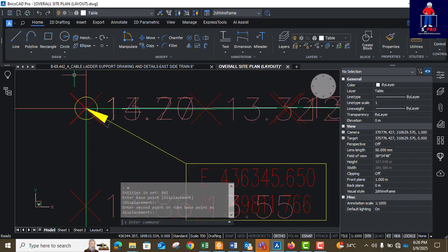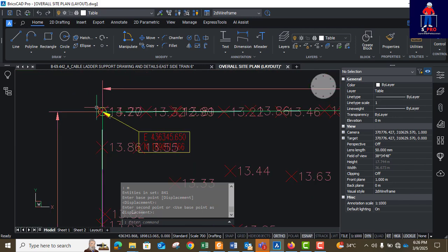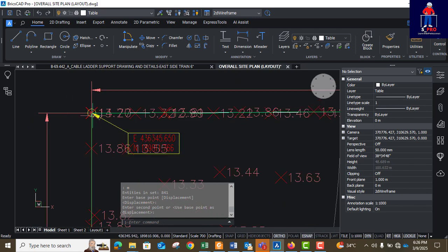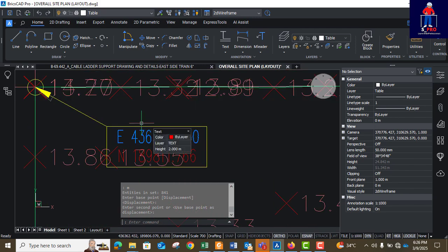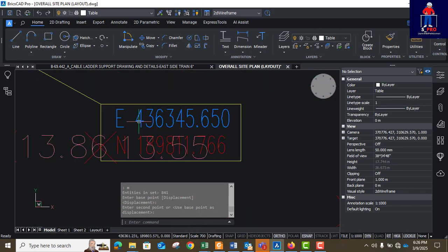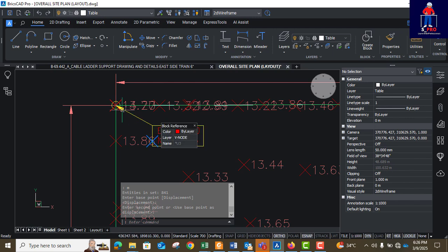What you do to confirm is check that this coordinate is actually listed in the report, and this particular point is labeled, so it has a label for you to know that this is where the coordinate is. I will show us how to check this coordinate. This is easting. This coordinate is what the surveyors will use to get this particular location. If you give a surveyor a coordinate of a particular point, when they get to site, they'll be able to use that coordinate to establish that point on site. That's why coordinates are very important.